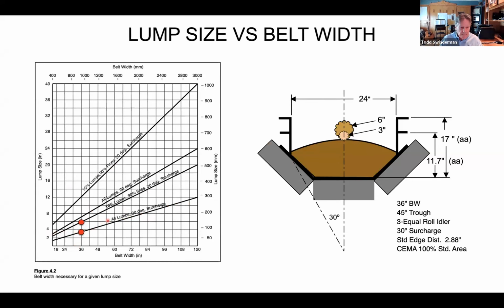So this is a case where you might look at this and say, oh, I better go back to my original calculations and run another calculation in terms of tonnage, belt speed and skirt board width. Try to get this point right at the bottom of my wear liner.